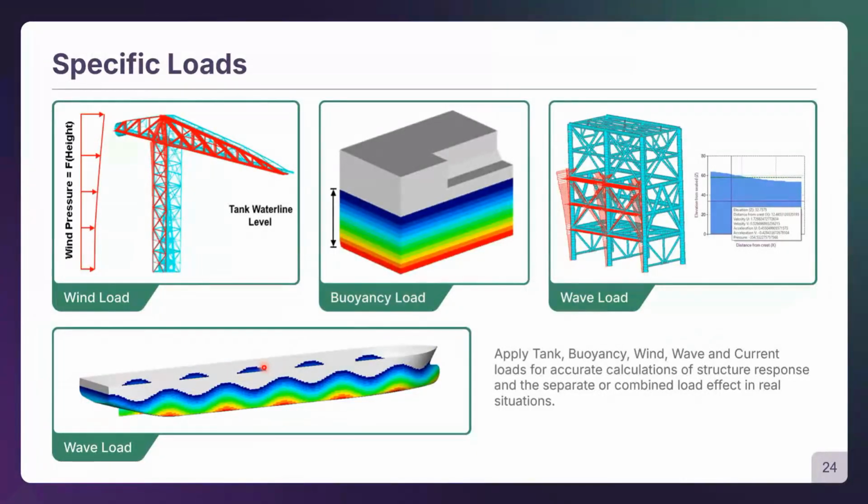SDC also allows you to create some specific loads, which, depending on the platform, will vary slightly, but in general, we have the possibility to create wave and buoyancy loads on your structure automatically, also wind or wave loads taken into account, also drag coefficients, wind drag coefficients, which for some of the standards can also be created automatically based on the geometry of your model. So that's also something which significantly decreases the load application time and also makes your life easier.